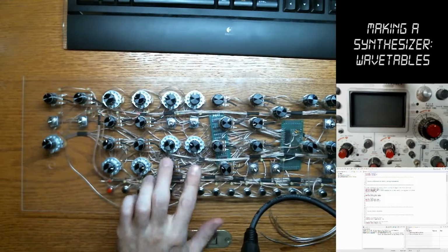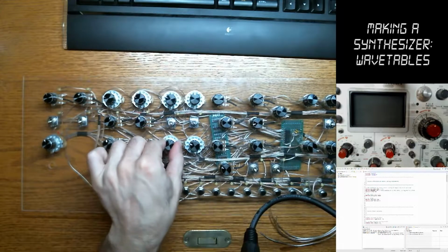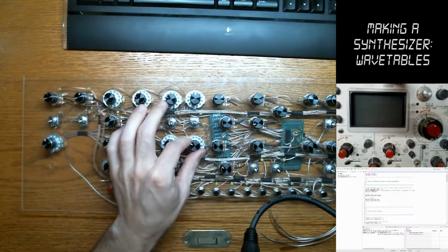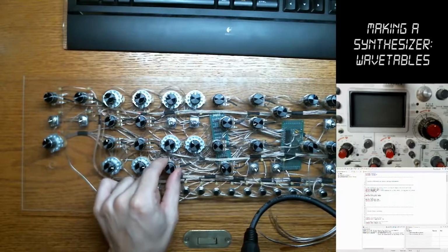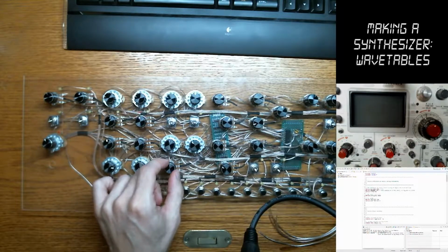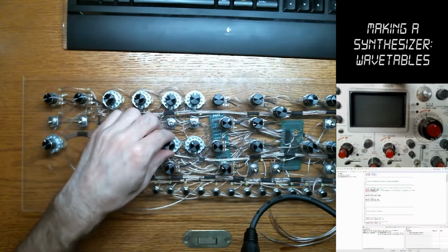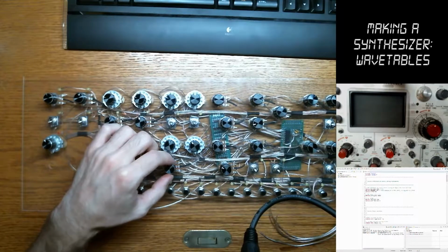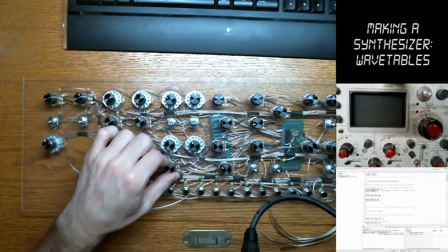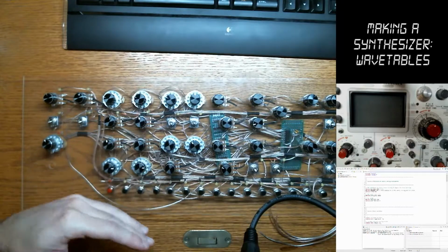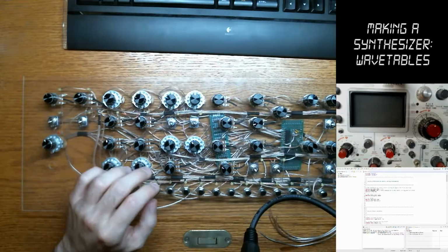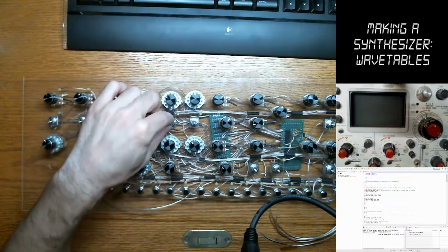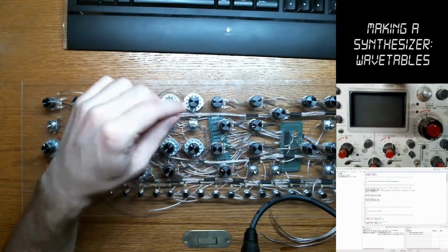Oscillator 2 has the same options here. You have a waveform selector, and then you also have an octave jump, and then you have one more potentiometer here, and this will be a smooth frequency adjust within that octave. So if this jumps every 12 notes, this will allow you to smoothly shift the frequency positive or negative, within the range of plus 12 or minus 12 notes. And then there's also some switches here, which I'll get to later.